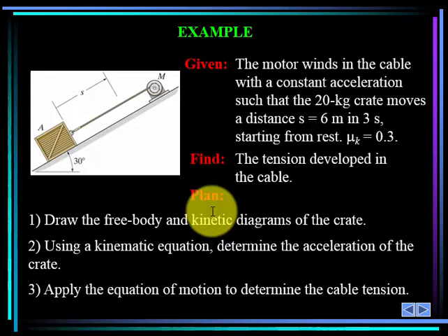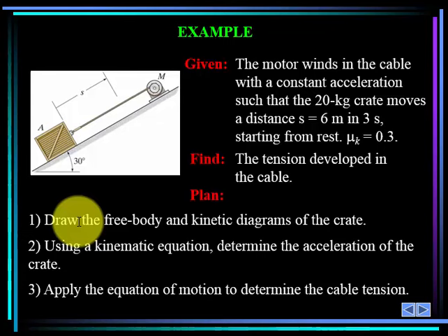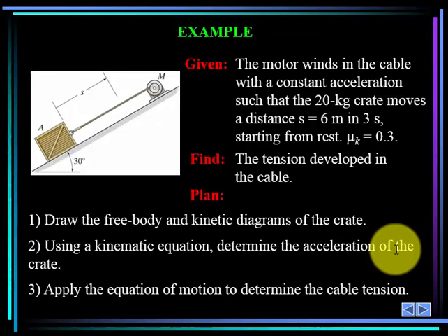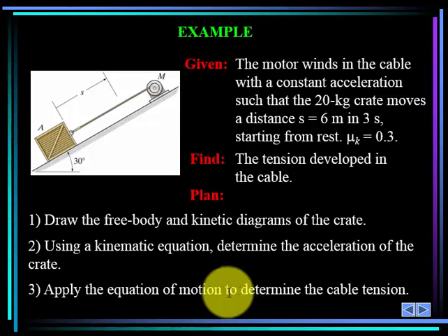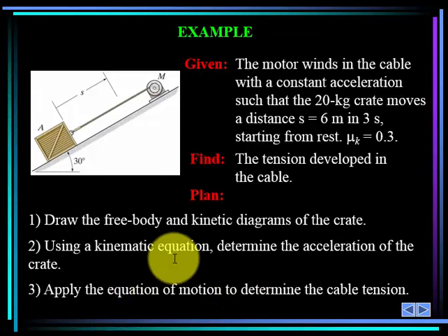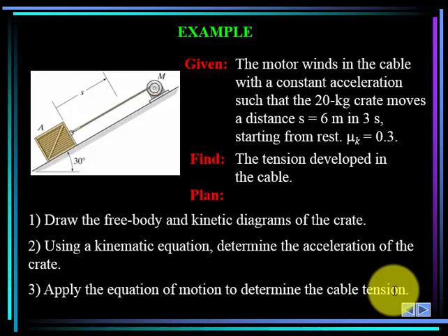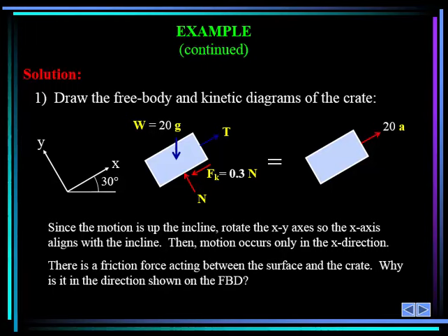So our plan will be a free body diagram and kinetic diagrams. I am massively dependent on free body diagrams. I often personally don't draw the kinetic diagram. We'll talk about that, because to me, it just doesn't say as much. If it helps you, that's fantastic. We'll write the kinematic equation that will deal with acceleration, and we will then apply the equation of motion once we can say something about acceleration to determine the cable tension or the cable force. So let's see how this problem proceeds.